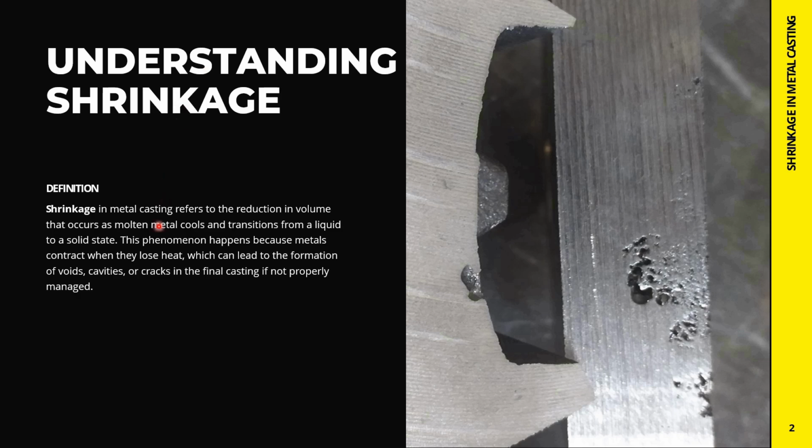By definition, shrinkage in metal casting refers to the reduction in volume that occurs as molten metal cools and transitions from a liquid to a solid state. This phenomenon happens because metals contract when they lose heat, which can lead to the formation of voids, cavities, or cracks in the final casting if not properly managed. These are the voids that are shown in this picture. You can look at the voids and cavities that occurred as it was not properly managed.